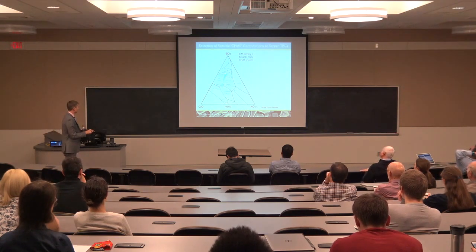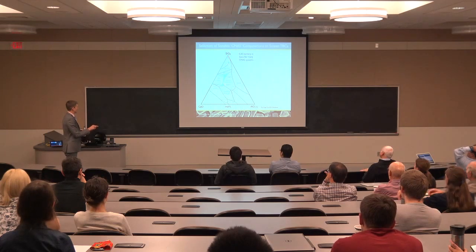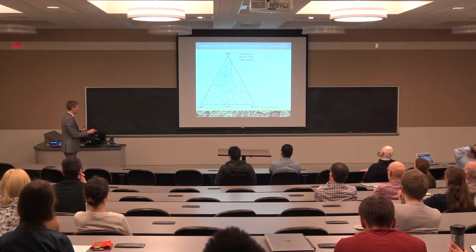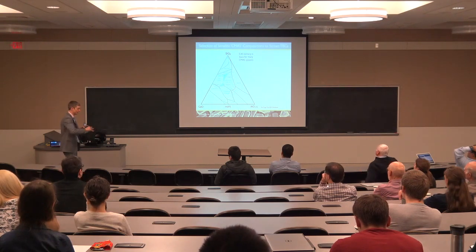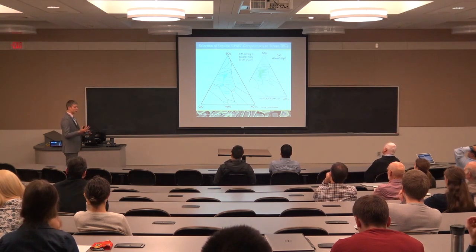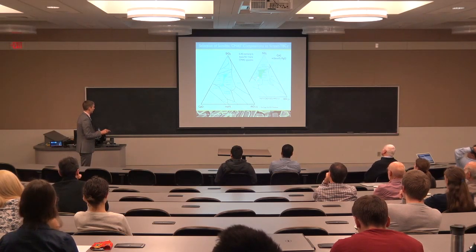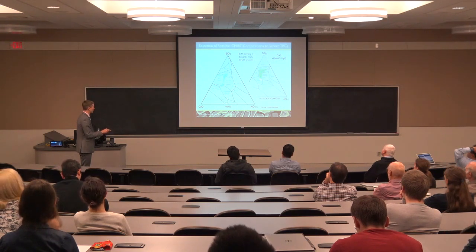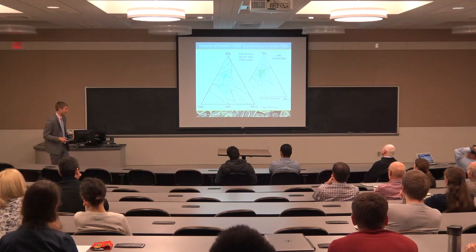We can say that at 1300, the range of liquids is pretty small. It falls in this little dark blue shaded area. And the range of deposits or debris that would cover is much broader. So if we want to understand the behavior of any deposit or debris that's out in this larger area, we can just pick a liquid that's in here and maybe a few outlying cases. If we start to add magnesia to the system, another constituent that's relevant, we shrink a little bit in this direction of the liquid field and expand in this direction, but again, we can start to map out what range of compositions is relevant to study.